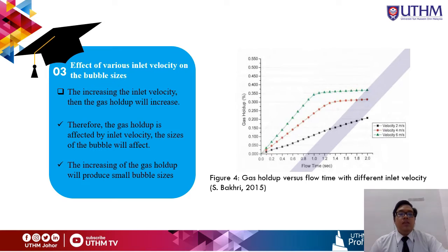Next, the effect of various inlet velocity on the bubble size. When the inlet velocity increases, the gas holdup will increase. Therefore, the gas holdup is affected by inlet velocity, and the size of the bubble will be affected too. The increasing of the gas holdup will produce a small bubble size.